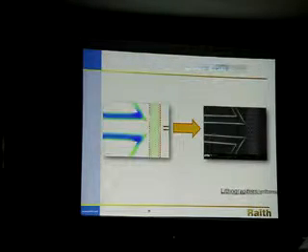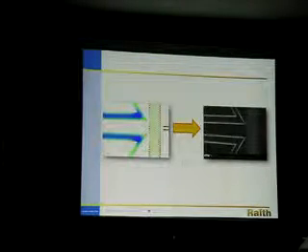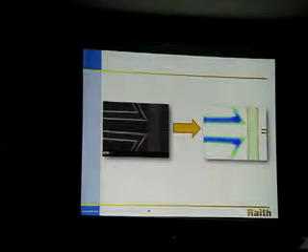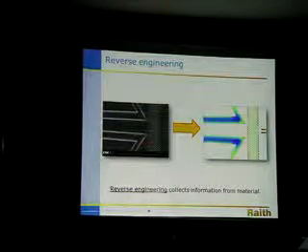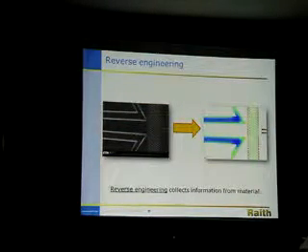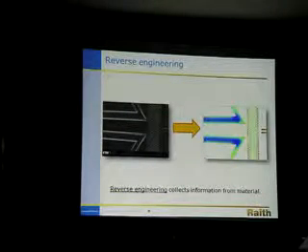In reverse engineering, you're basically doing the opposite. You're starting with an unknown chip, and you want to record SEM images over very large areas in order to ultimately extract the GDS2 file, and then we have customers using proprietary solutions to even produce the net list and even the schematic.